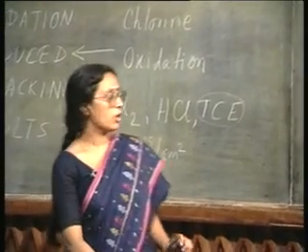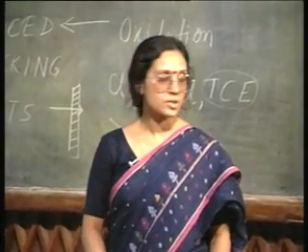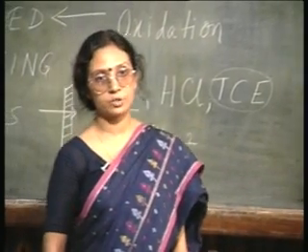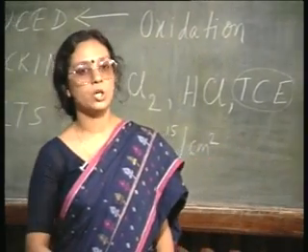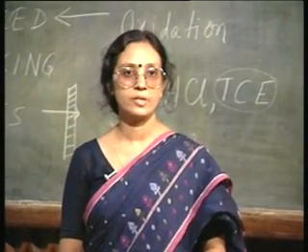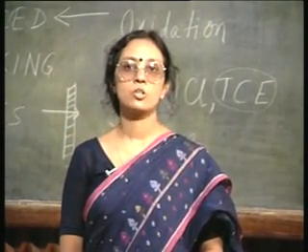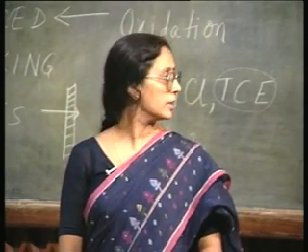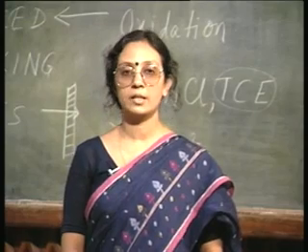Now, the origin of these interface trapped charges are primarily silicon dangling bonds. You see, before the oxidation, when we have the fresh silicon surface, the surface means loss of crystallinity. So, on the surface of the silicon, there are a large number of dangling bonds.